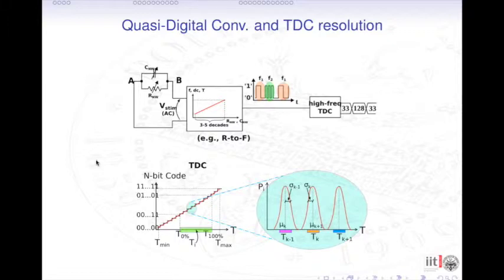It is important to notice that the least significant bit in this approach is related to the standard deviation, to the jitter of your oscillation, and so the standard deviation associated to the measure of the mean value of your oscillation period.